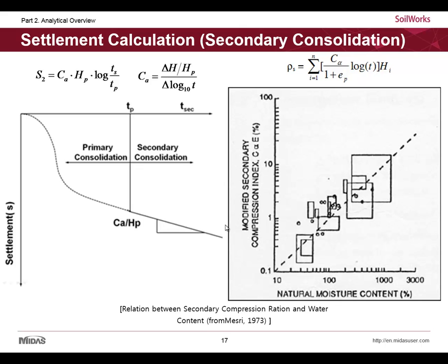If this consolidation seems to be critical, we can usually consider the solidification method, or excavating and replacement of soft ground. Some engineers used to exclude this from the total settlement. Actually, there is no right or wrong answer, so it depends on the site condition, the importance of adjacent structures, and engineering mind. SoilWorks calculates the primary and secondary settlement separately, and then you can select the primary or both for the total settlement.